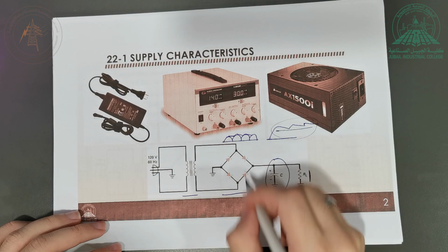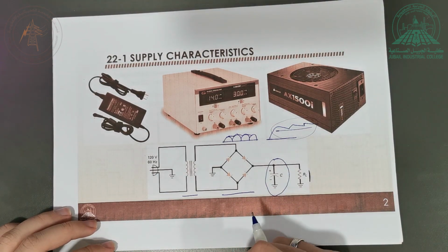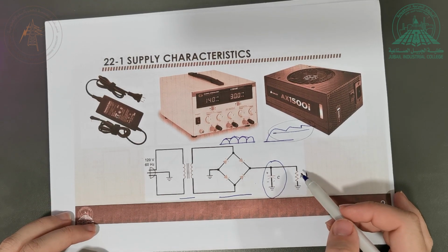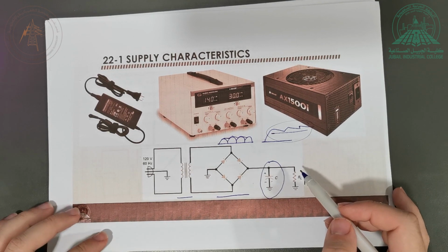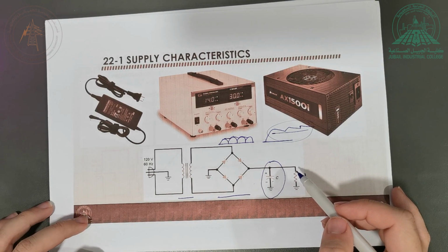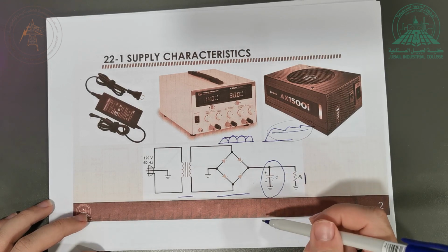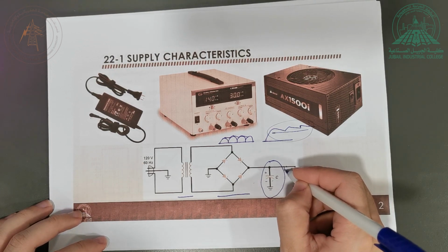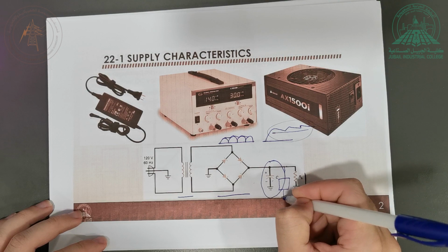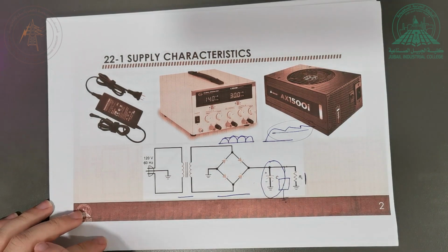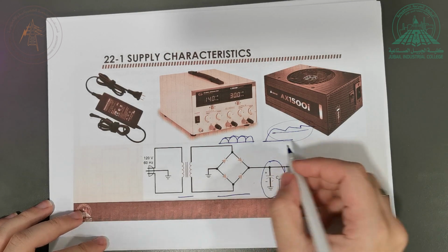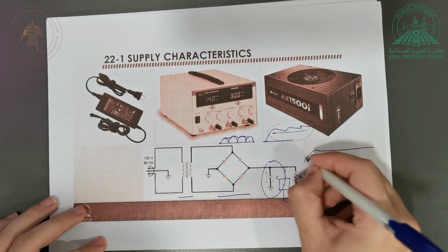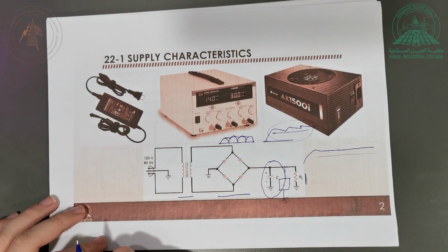And you have seen that these ripples, I can reduce them by increasing the size, increasing the capacitance of the capacitor. But we said that this is not the most practical solution, because capacitors usually have large physical sizes, and as a result, it's not advisable to have too large values of capacitors, and instead we can have here a power regulator. So the power regulator here is going to fix the output voltage to the level that I need it to be, right? So the final output that is going to reach the load, hopefully, if everything goes fine, should look like that. Which is something that's constant with time, which basically presents a DC signal.